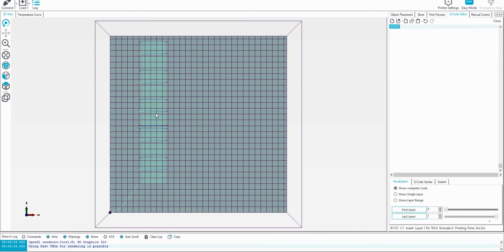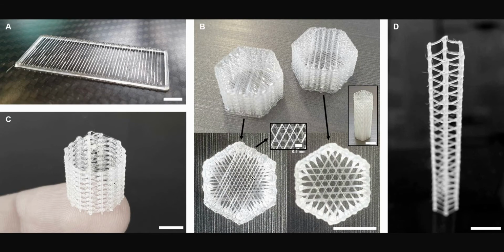So if we repeated this column with four different temperatures in 4 different columns, we now have 400 different combinations of temperature, speed and extrusion rate, each printed for 2 strings, so we could identify what the best combination of print parameters is to print very neat strings. And this is only taking 3 minutes, so for that whole calibration print of 400 parameters it might take 10 to 20 minutes. And that's how we can achieve really nice printed structures where we've got strings down to 1/10 of the nozzle diameter, hundreds of them all being printed precisely.